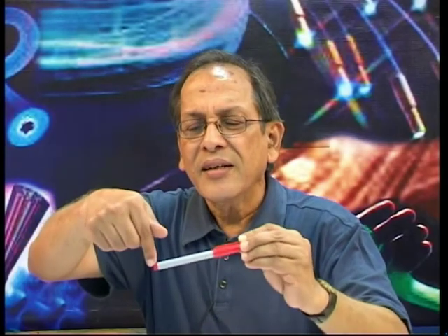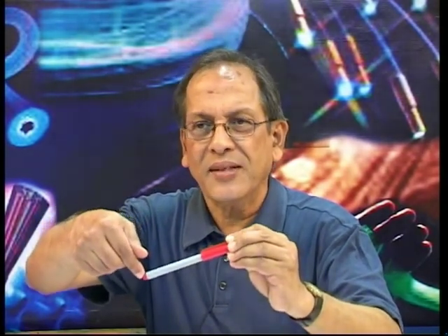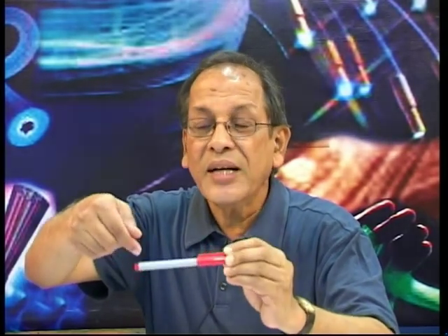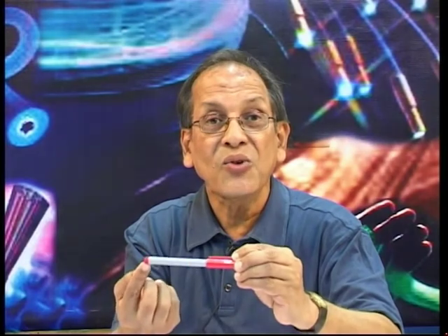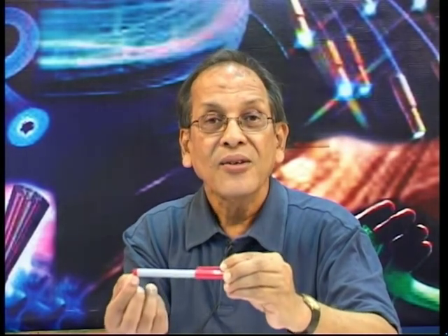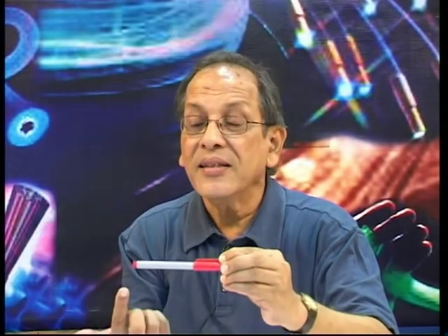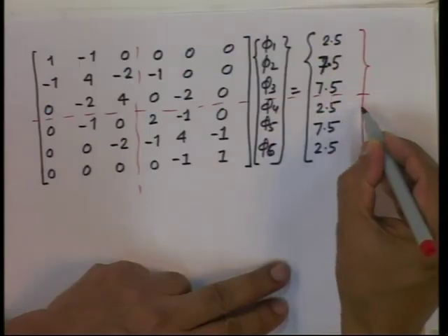Either the load is there, yes, you can always solve a problem with a cantilever with a load, then this will deflect, there is no problem, that is applied to the node. But if that node happens to be constrained, if you put a support there, then that load will directly go to the support and you must get the proper reaction. So, wherever you have dependent variable prescribed, there must be reaction. So, we always say that on these there must be reaction here.